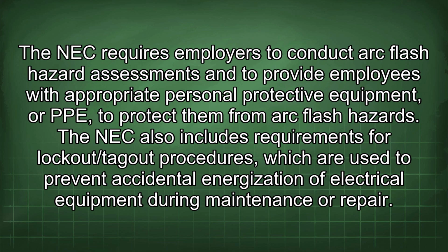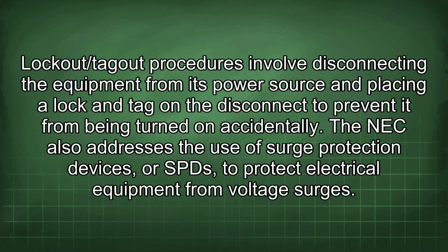The NEC also includes requirements for lockout/tagout procedures, which are used to prevent accidental energization of electrical equipment during maintenance or repair. Lockout/tagout procedures involve disconnecting the equipment from its power source and placing a lock and tag on the disconnect to prevent it from being turned on accidentally.